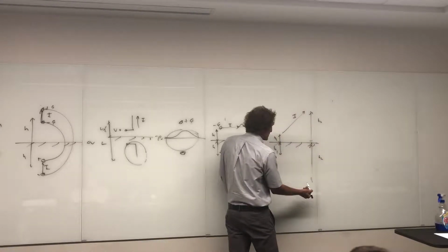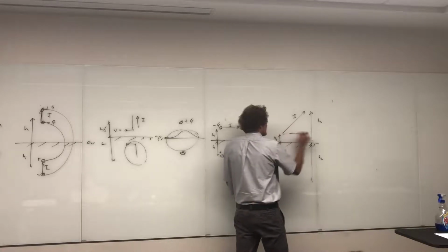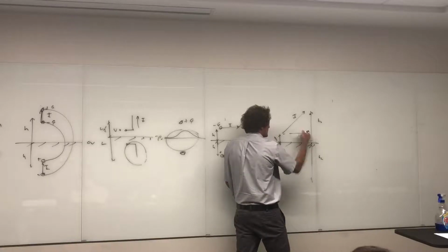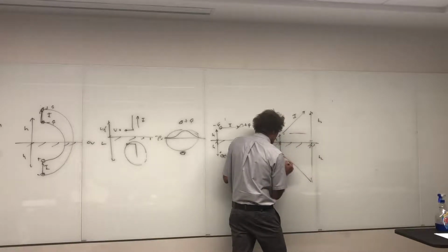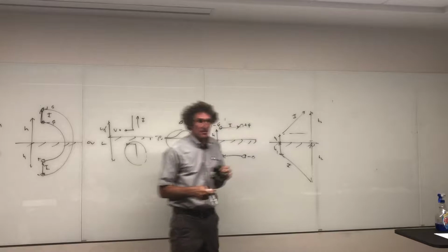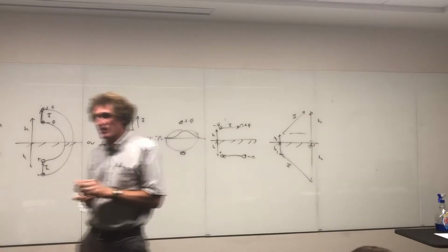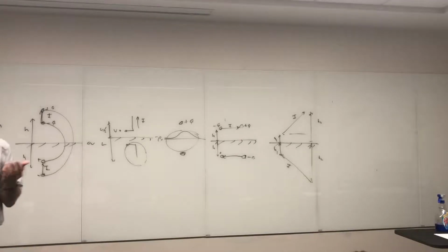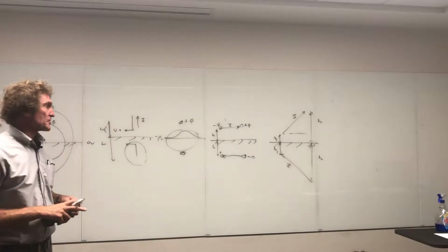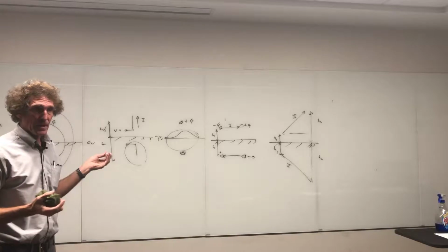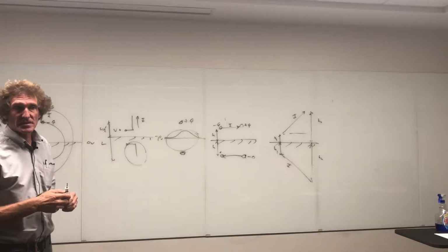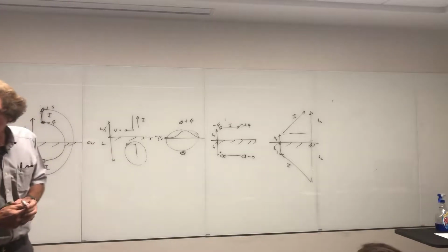I know the verticals have to go in the same direction. The vertical component of this is here, so the vertical is going to be going up. What about the horizontal? Opposite. It's going to do this. Can you all see that, class? With me? Verticals same, horizontals opposite. And that would be the method of images applied to an arbitrarily straight wire antenna at a bent angle. Sometimes folded dipoles look like this. Just realize this. That's the only thing I'm showing you. Something to take from this.